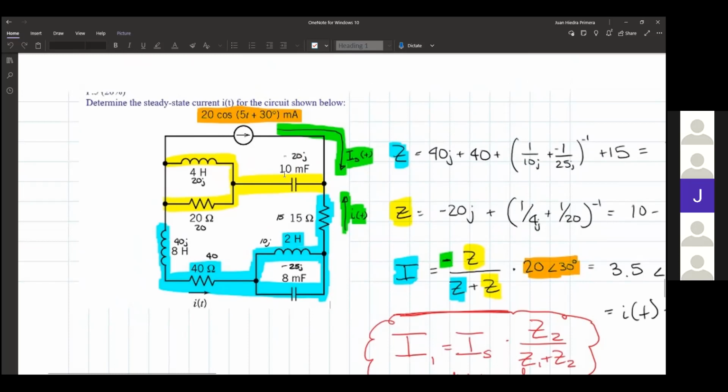We have this parallel branch. Do note that they might be trying to trick you here. This node right here is all one node. There it is, cool. All of this, you should treat it as a single node as it is in short circuit with itself, and thus has the same current flowing through it and the same voltage from ground at that point.